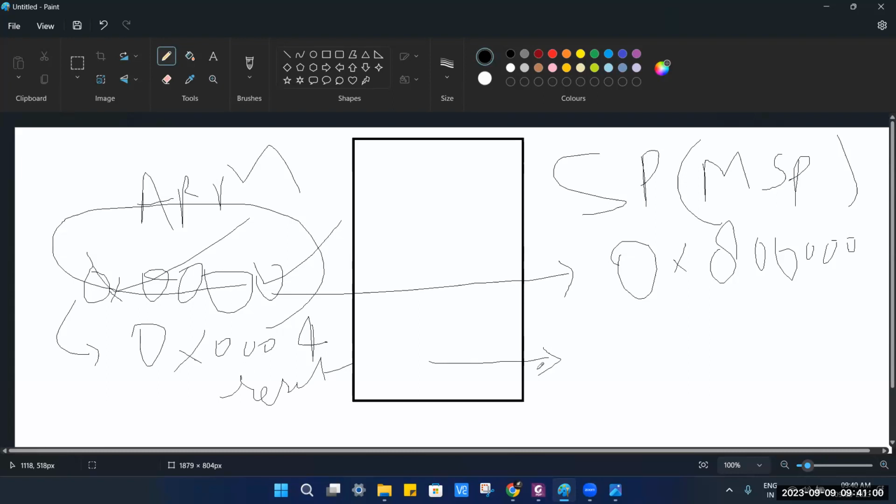Now it depends whether the execution code will start from flash, from ROM, or from SRAM. It depends on the boot pin you have set. So this is mostly the reset sequence. First it will fetch data from 0x00, but in the case of STM, the flash starts from 0x0800 something. So it will set it from there.